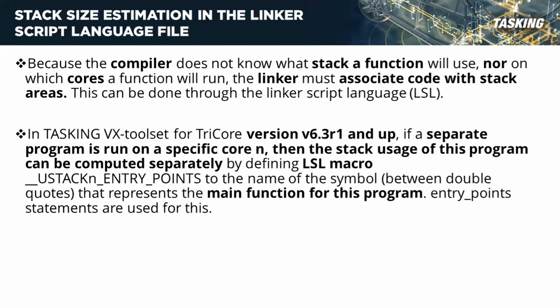This is the responsibility of the linker. So the linker has to define all of this according to the device that you are using. And in order to configure this, you have to make certain changes to the LSL, or linker script language, file.